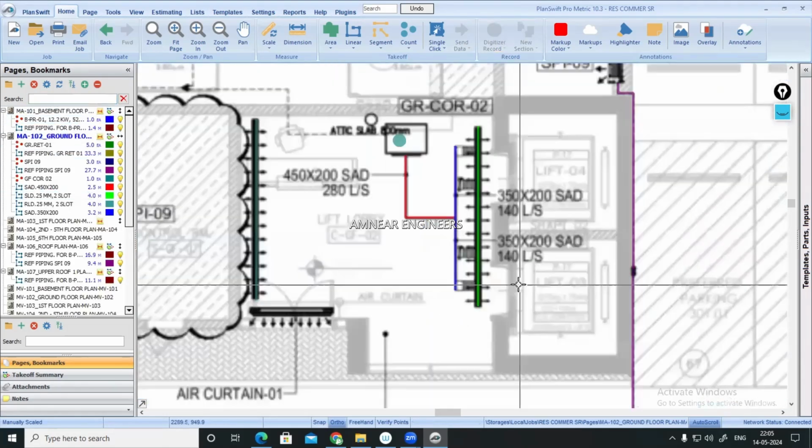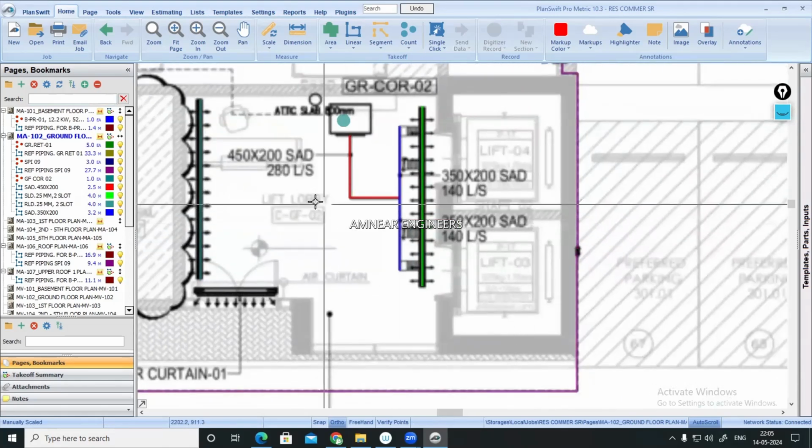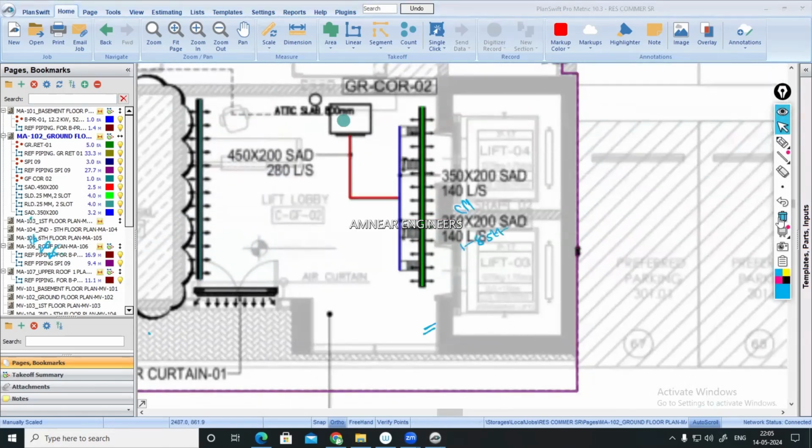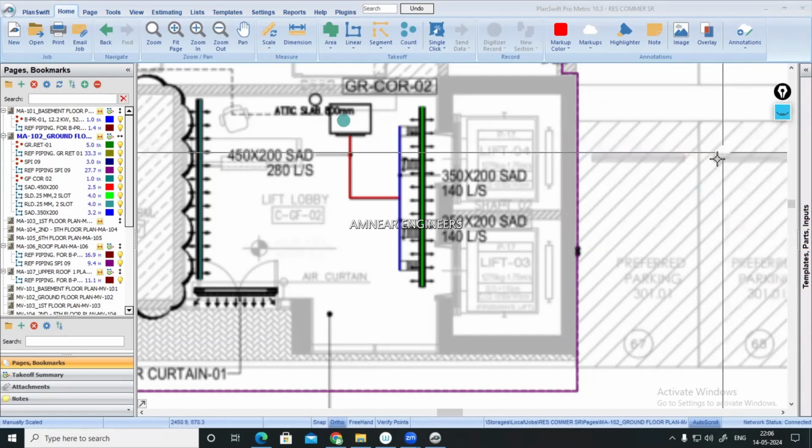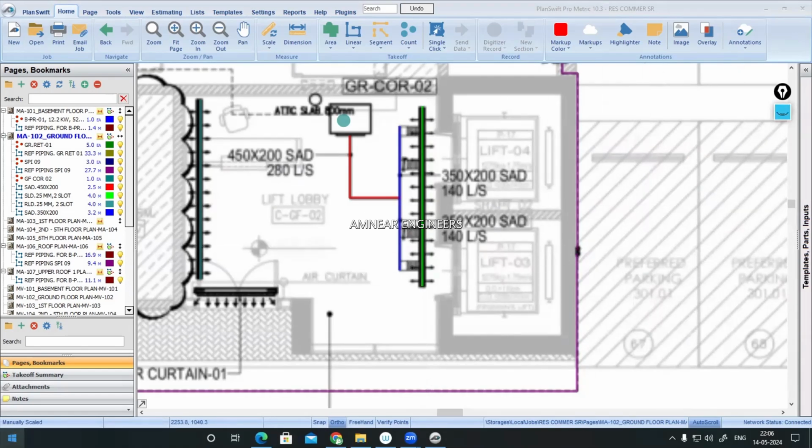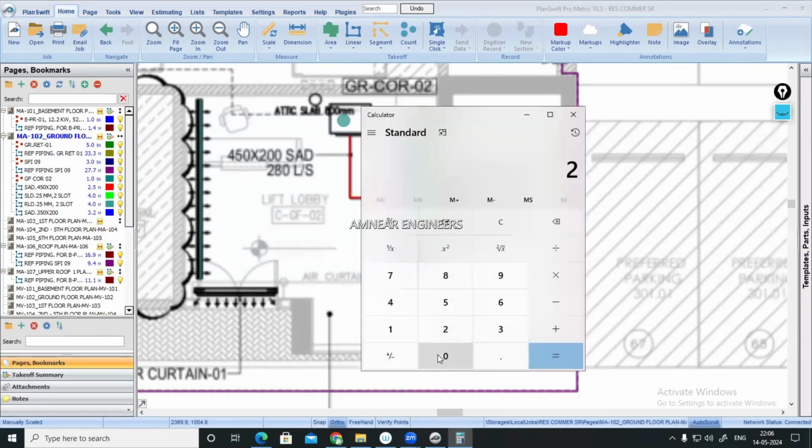Okay. Now, flexible duct diameter I should find. 280 liter per second. They are delivering 280 liter per second by the help of 4 number of flexible duct: 1, 2, 3, 4. Correct. 280 liter per second has to be delivered by 4. So 280 divided by 4, what might be the flow rate of each one? 70, right? So the flexible duct flow rate is 70.